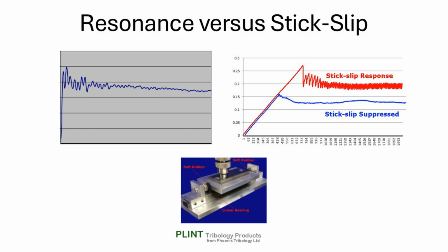It's important not to confuse resonance with stick slip. The former is essentially a symmetrical waveform, whereas stick slip is not. We can promote stick slip behavior by including a degree of compliance in our system. This emphasizes the deflection during the stick phase and the rapid decrease in friction during the slip phase. We end up with a sawtooth, not a symmetrical waveform. This is a nice example of altering the system response by altering the stiffness in the friction plane.